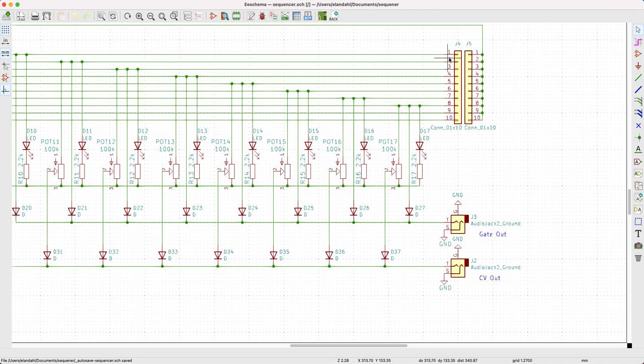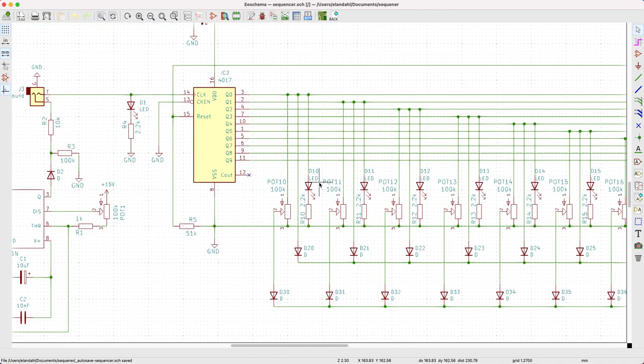And the difference between J4 is each of these are individually connected to the outputs, whereas J5, all of them are connected together. So a jump from one across connects this output to this line, or jumping 6 across connects 6 to this line. And this is a mechanism for doing the resets at different times. Because this wire runs up and over and into the reset of the decade counter.